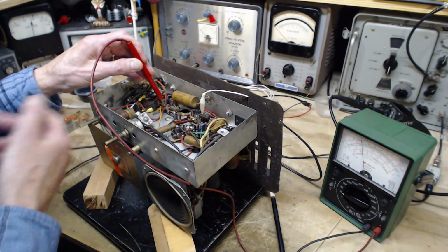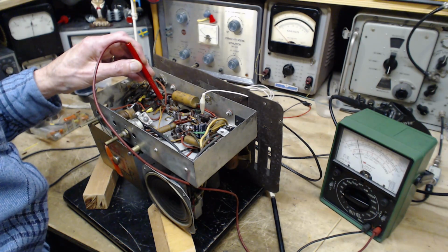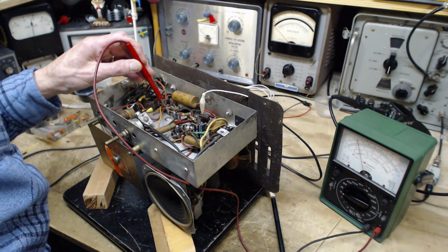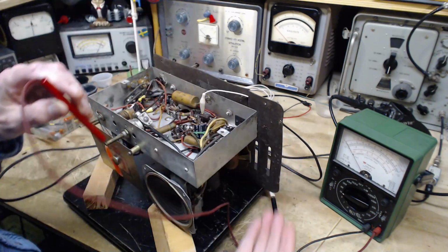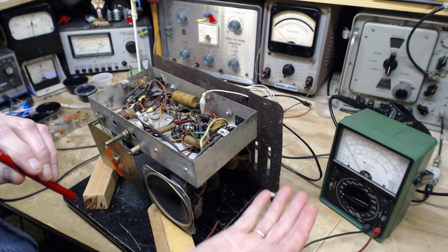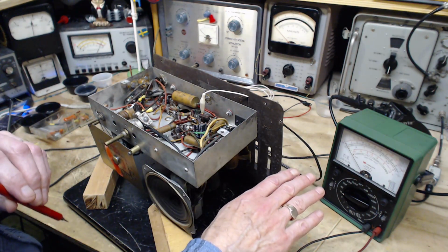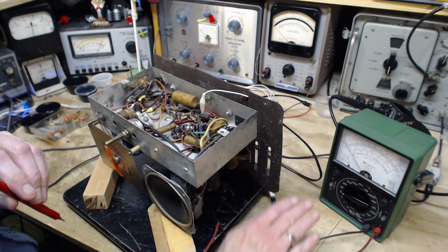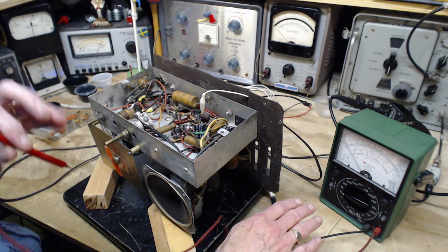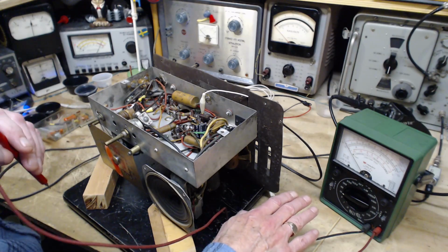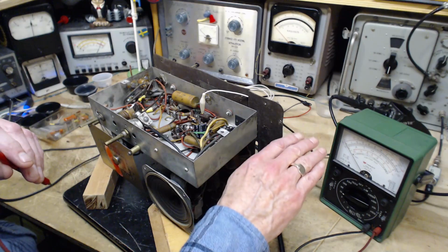So there is an effect called self-biasing. There can also be in some radios a base bias. So they set up a circuit to produce a certain bias on the tube, and then the AVC will drive it more negative if needed. Otherwise, with no AVC input, the bias will end up resolving itself at some set point, not zero.